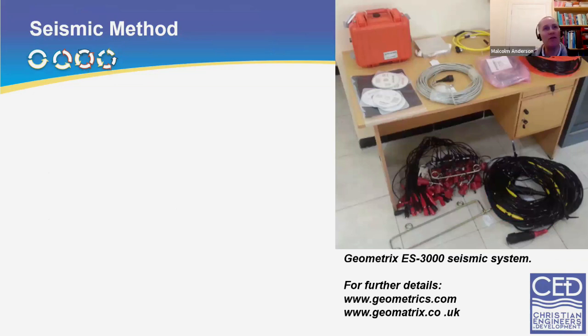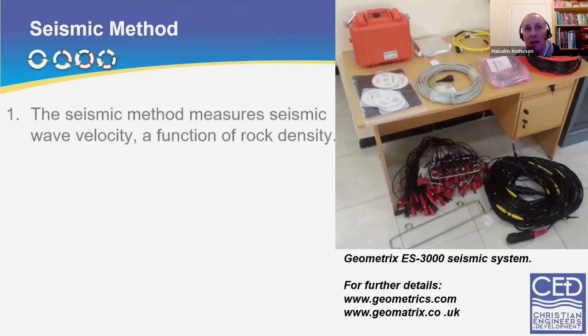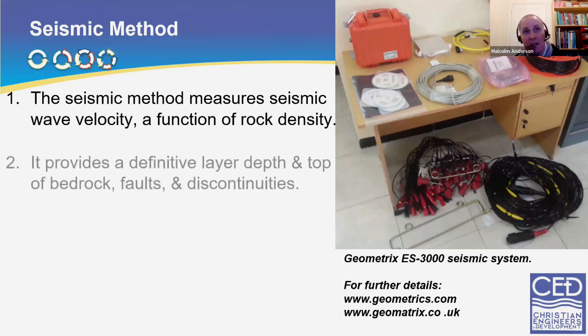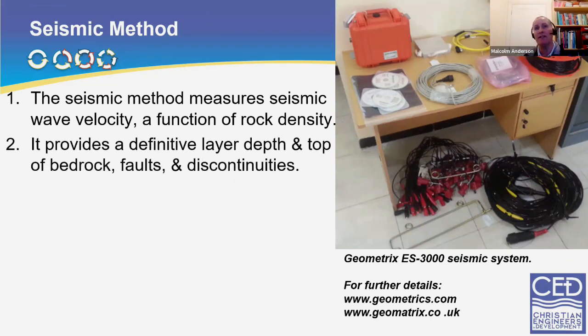Okay, so now I'm going to just close off with a couple of methods that generally we don't use in groundwater because they're either too expensive or they're too shallow. So first of all, the seismic method, which most of you will be familiar with. Obviously, it measures the seismic wave velocity, and the velocity of the seismic waves is a function of rock density. It provides a definitive layer depth, and top of bedrock, identifies faults and discontinuities, so it's a very powerful method.